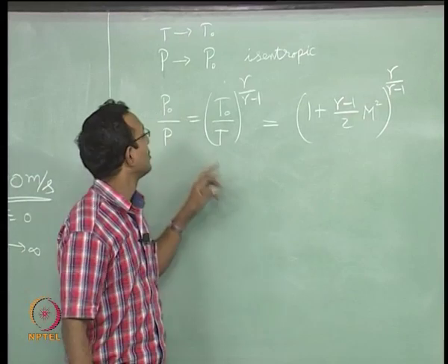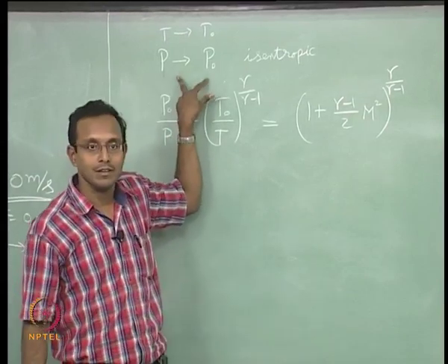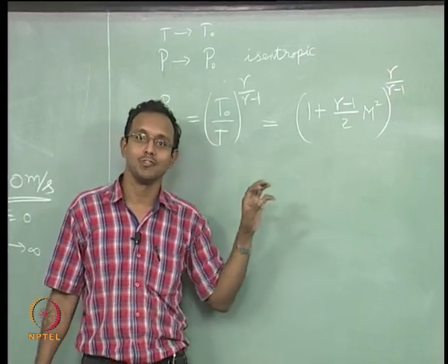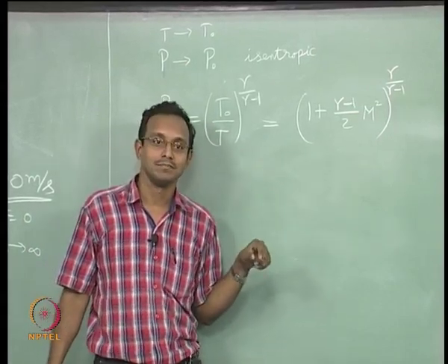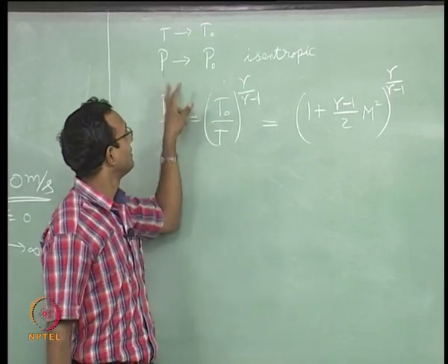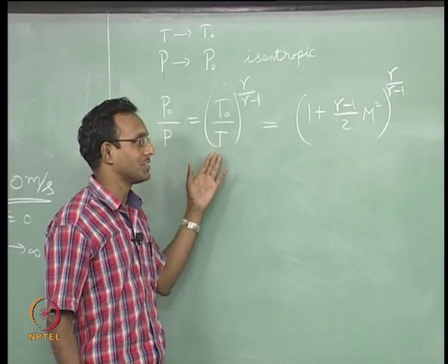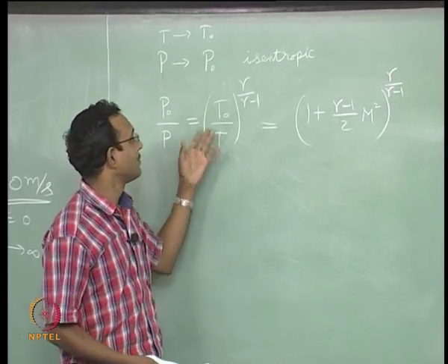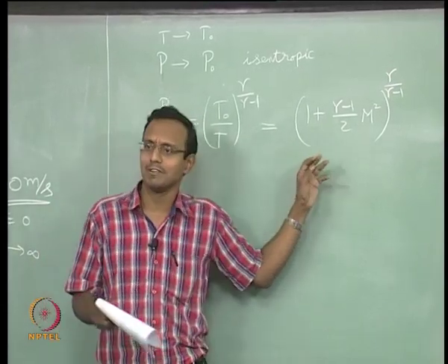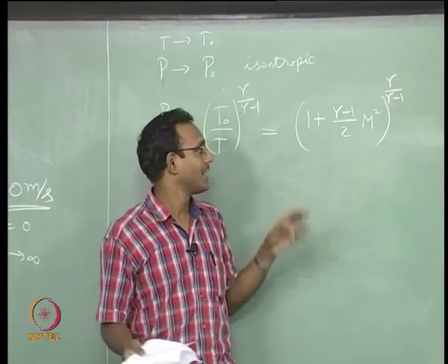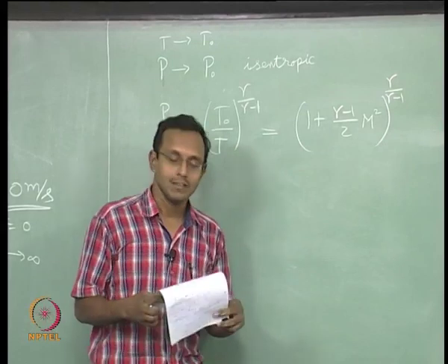It needs to be isentropic only for pressure. For temperature, it is enough that the energy equation says there is no more q dot in, okay. If that is the case, then that expression is valid. You just derived it from energy equation just today, right. When we derived it that way, we found that it was directly equal to this directly from energy equation, that was only for adiabatic steady flow, and I got to this point, okay.